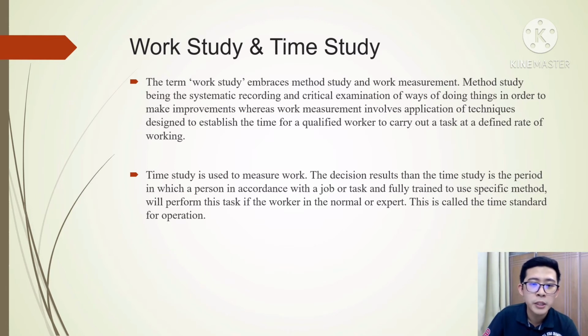Method study is a systematic recording and critical examination of ways of doing things in order to make improvements, whereas work measurement involves the application of techniques designed to establish the time for a qualified worker to carry out a task at a defined rate of working.